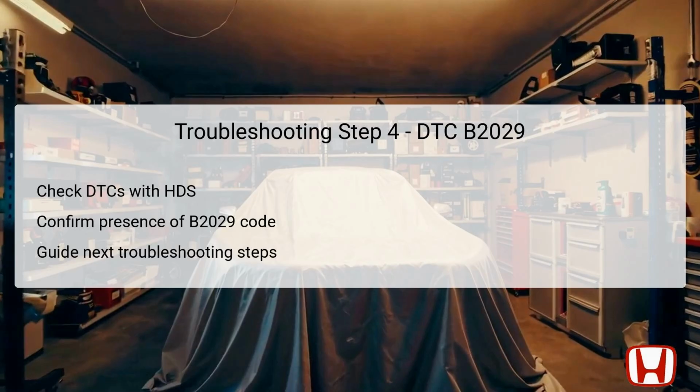The fourth step in the troubleshooting process is to check for DTCs again, using the HDS after the previous steps. This step is pivotal, as it determines if the DTC B2029 is still present or has cleared after performing the initial tests. If the code remains, it indicates a persistent issue needing further investigation. Conversely, if the code is not present, it may imply an intermittent fault or connection issue.